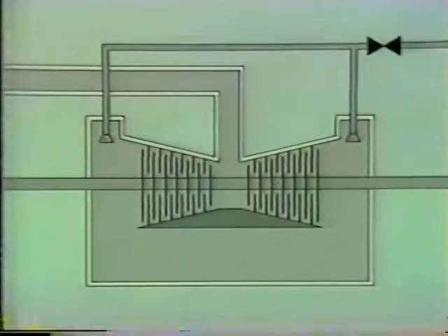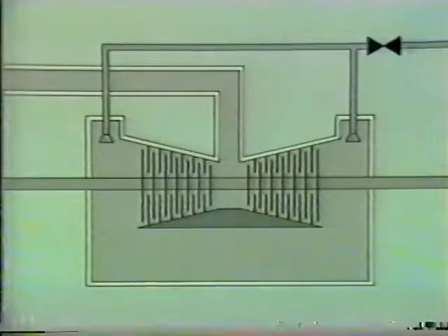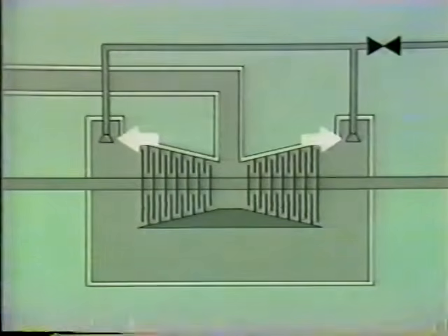To control the temperature of the exhaust hood, a water spray system is provided in each low-pressure turbine. This system consists of nozzles installed downstream of the last stage blades. The nozzles spray water into the exhaust hood, which cools it. A control valve controls the flow of water to the nozzles, and this valve is operated to maintain the exhaust hood temperature at about 125 degrees Fahrenheit.